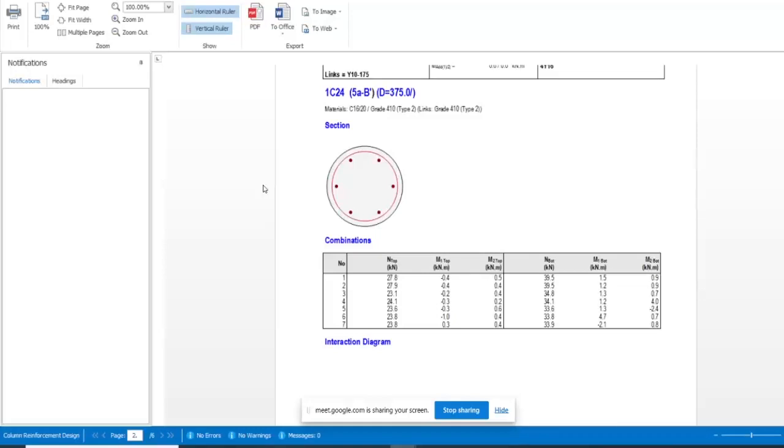Alright. What about for square or rectangular column? What's going to be the minimum number of reinforcement? I think for a square and rectangular, we have four as minimum. Four as minimum. That's the number. Now, for percentage for columns, what's the minimum percentage of area of steel?